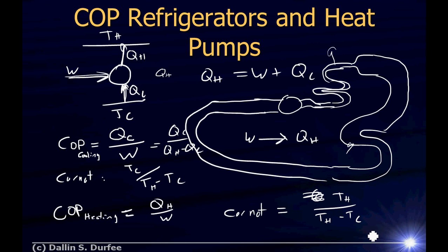So you have this connection between the inside and the outside that heat can leak through and whatnot. So you want to be able to get a big gain to make up for the mechanical imperfections in your system. But the very best efficiency you can get is the Carnot efficiency, and that goes down as the difference between the outside cold temperature and the inside hot temperature gets bigger. So at a place like Utah where it gets really cold, a heat pump is not as useful as it is somewhere where it doesn't get that cold, but you want to save on energy anyway, alright?